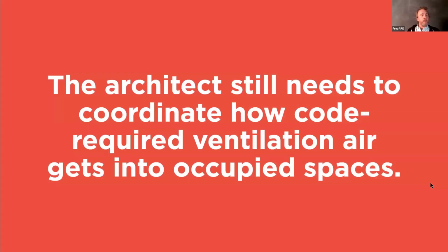Bear in mind, don't assume that VRF systems will solve your fresh air requirements. You will still need to coordinate any air ventilation, and so you're going to possibly need to calculate air changes per hour and stuff like that. That may pop up on the ARE as well.